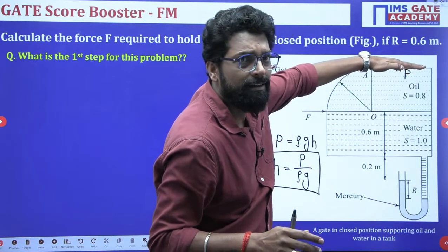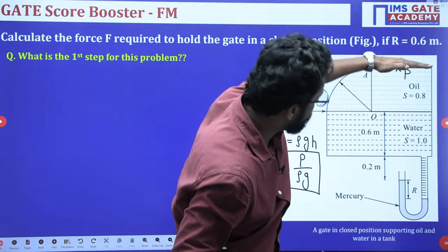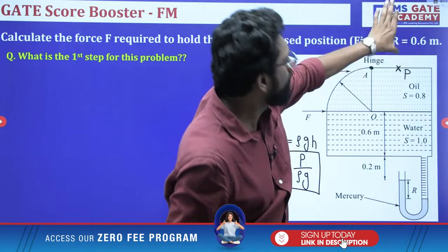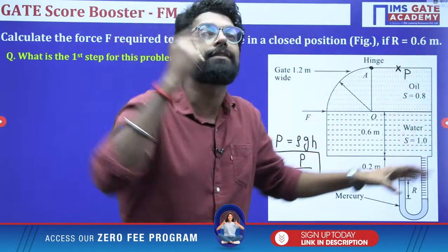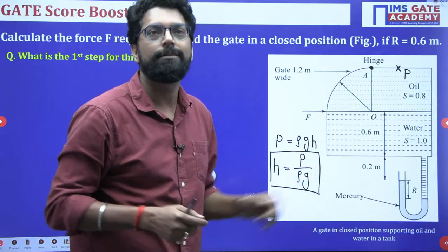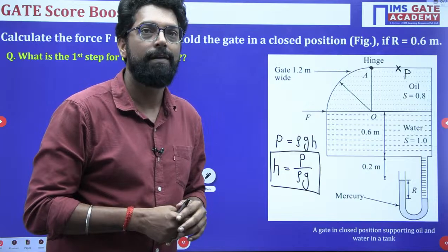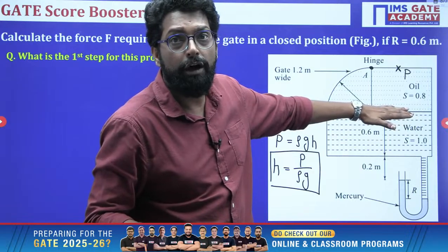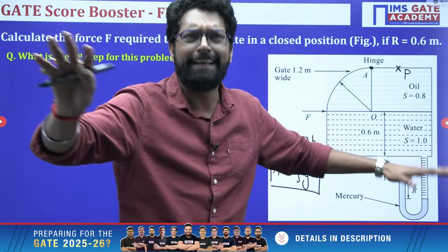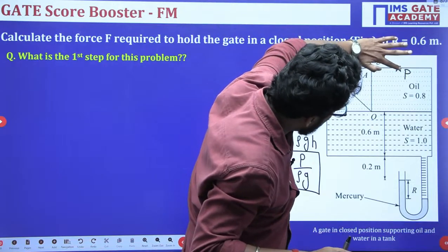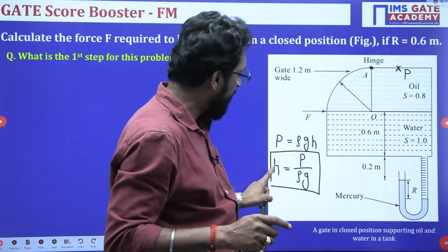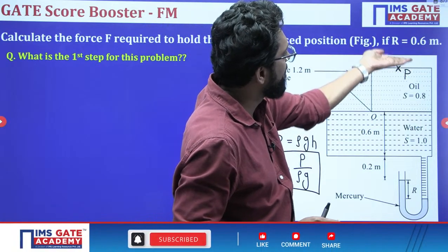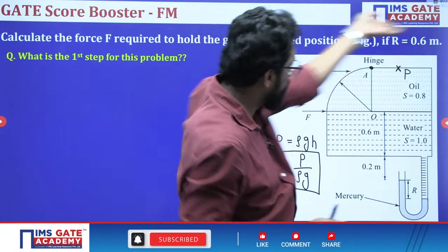This is pressurized. So this pressure is equivalent to how much fluid column up to the free surface? Then you have to find the free surface, then calculate. This is a very good problem, I am telling you. No, don't draw anything here. Just calculate this pressure P. Once you have the pressure, you can find the head. How much equivalent head will develop? And then you define a free surface.